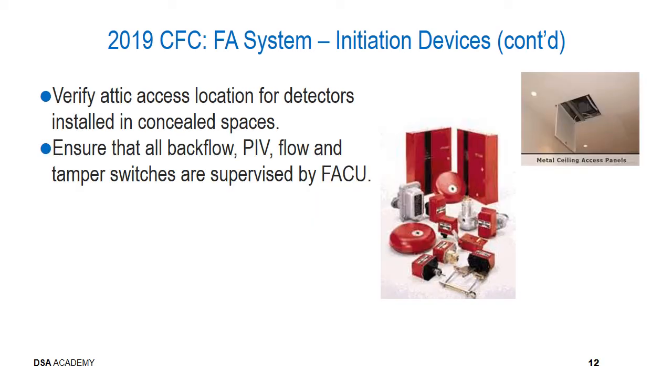Verify attic access location for detectors installed in the concealed spaces. Ensure that all the backflow, PIV, flow, and tamper switches are supervised by the fire alarm control unit. During testing, the panel should record and reflect each one of these devices as a supervisory alarm.